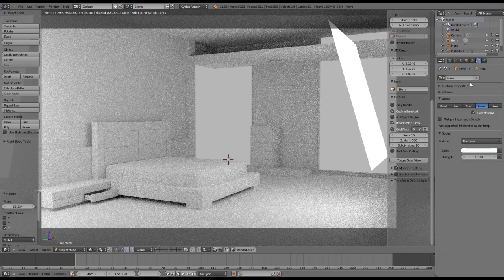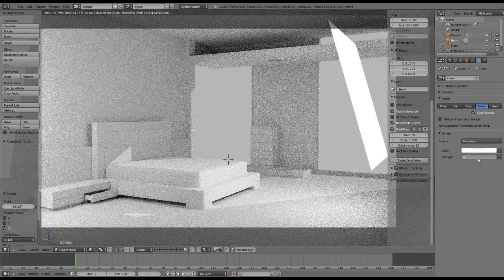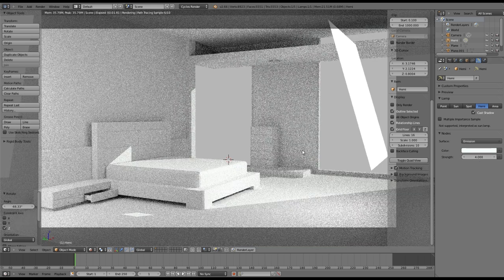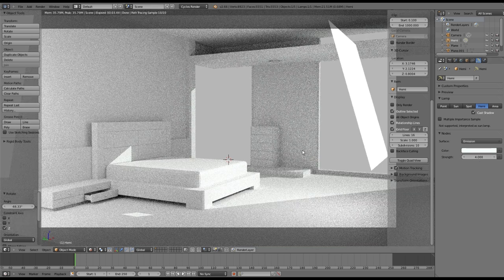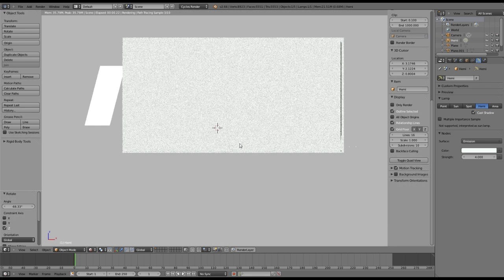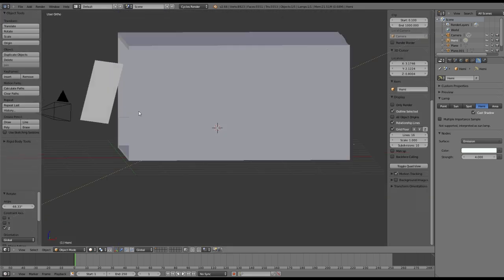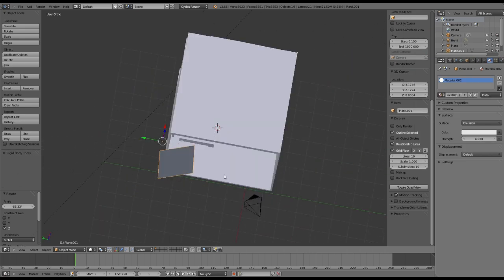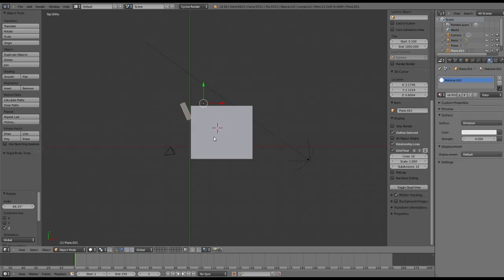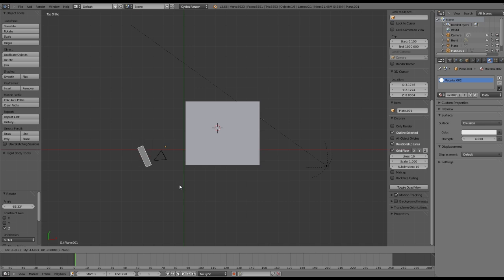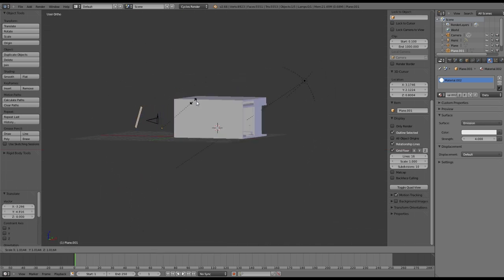And I could turn my hemisphere light back on, so to 2. And then you've got combined lighting, so you've got the sunlight plus the hemisphere lights. Now, in photography a lot, they'll have like a diffuse light behind the camera, and you can set that up as well. So if I just go into my viewport, and go to solid again so I can see everything, I might grab this emitter here, go into aerial view with 7 on my numpad, G to drag it behind my camera. I'll just check to make sure that's right, yep.